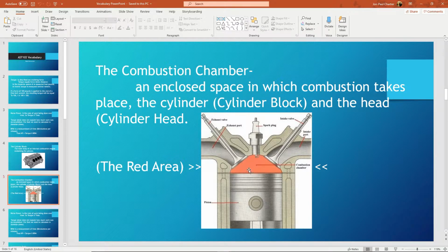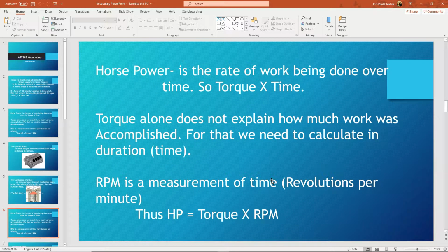However much room is in here. Some older engines are designed that when this valve opens, this guy here, if he was all the way open out to here, he would never touch this piston. Newer engines, though, this combustion chamber is so tight, which makes better efficiency and better power, that this valve might touch the piston. So we call that an interference engine. And this is why you absolutely need to do your timing belt. Anyway, so sorry for the duplicate slide.